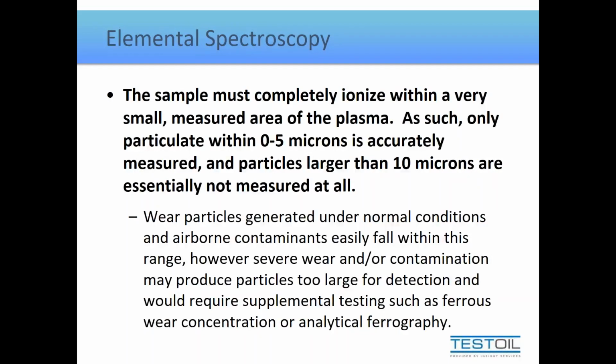Now, as I've got listed in the subnote here, wear particles that are generated under normal wear conditions will definitely be under 5 microns. Wear particles that are generated by severe conditions, where we've got insufficient lubrication or contamination or misalignments or whatever it might be, those will start to be outside of that range, and therefore they will not show up here. So you might be lulled into a false sense of security that your system's looking good. So keep that in mind.